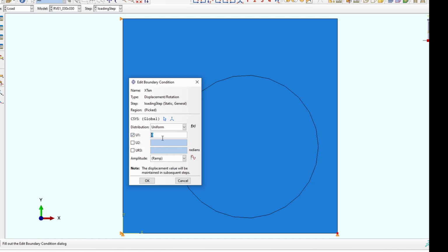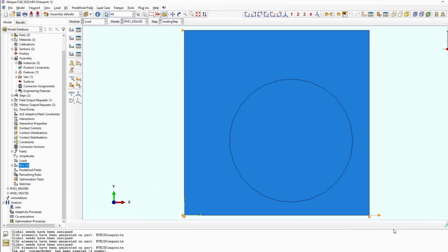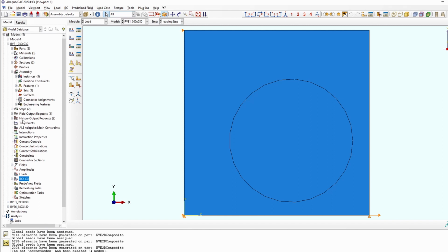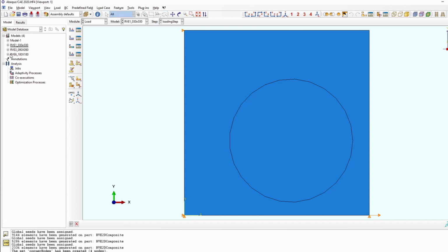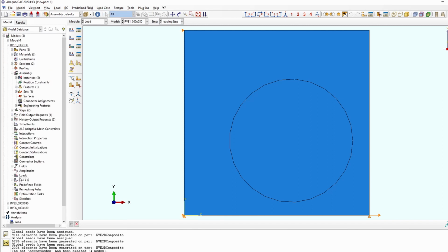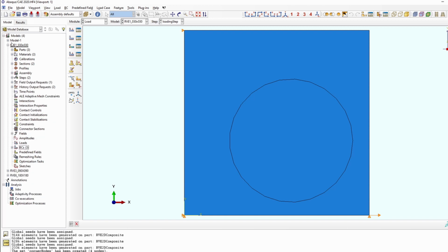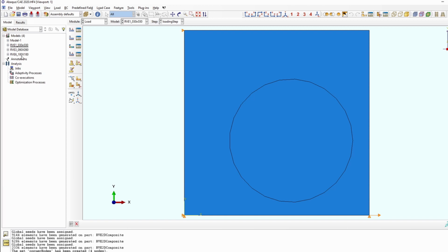Originally this size was 30, so if we do 20 or 30% of that, let's do 30% of that, which gives us 9. Okay, so 30% of 30 is 9, right? So that's our displacement created effectively the way it should be. Boundary conditions all in place, loading history is accepted. So we can do the same for the other two cases quickly.